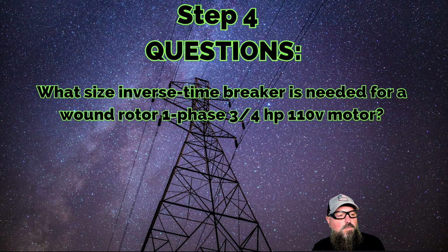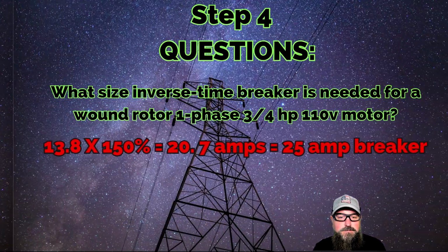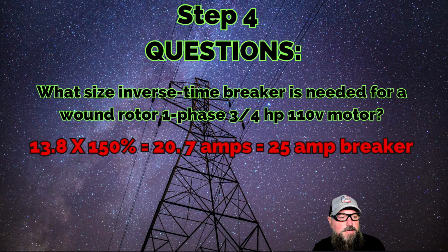Next question, what size inverse time breaker is needed for a wound rotor single phase 3/4 horsepower 110 volt motor? Go ahead and pause now. So you've got 13.8 times 150%, 1.5, equals 20.7 amps. The next breaker size is going to be a 25 amp breaker.